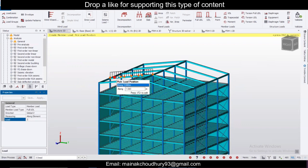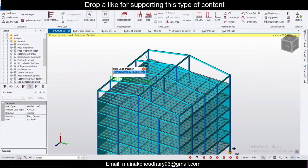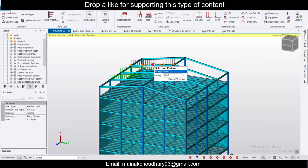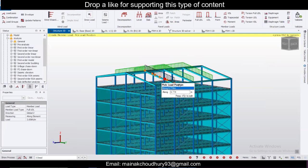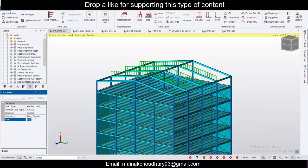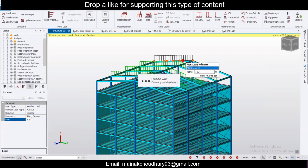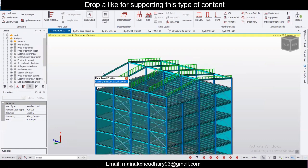And also remember, in the middle, if it is 3, then at the ends, it will be half. So I'll just explain in a moment. Okay. So here it is 3, here it is 3, and you can provide 3 everywhere, but later also you can change. Here it is 3, and here it is half, like at the end 1.5. So it is 1.5 here, 1.5 here. Just rotate it to a proper view, 1.5 here. This is for the dead load.